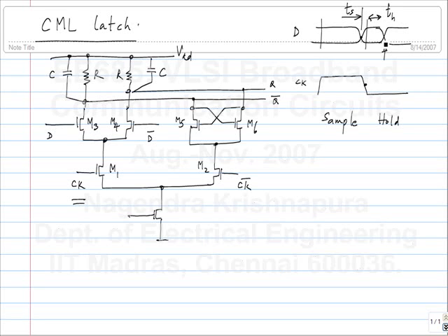One thing to observe is that it takes a finite amount of time even for the clock, the lower differential pairs to switch, because of finite rise time and the non-zero switching voltage of the differential pair. Okay. So why do we have this setup and hold times? So now explain to me which pair affects what? M3 and M4 and M5 and M6.